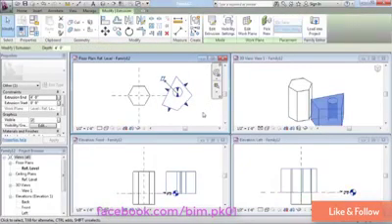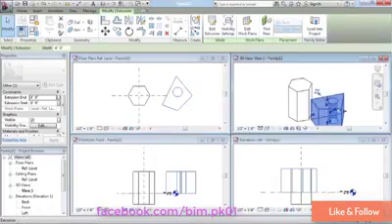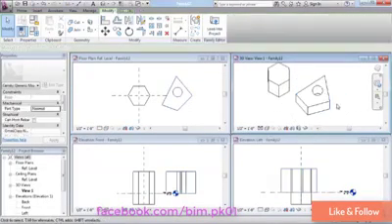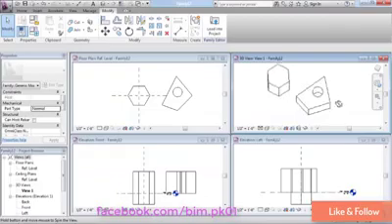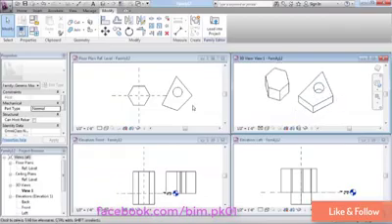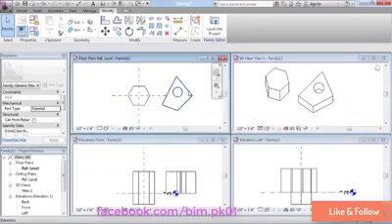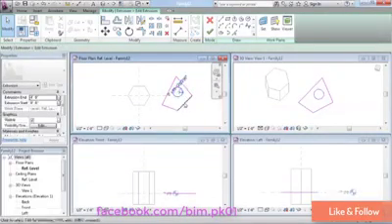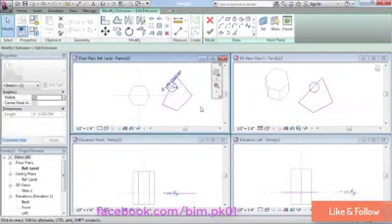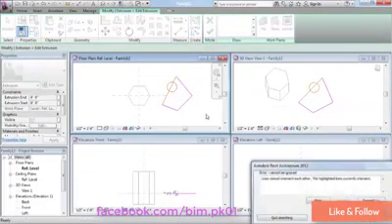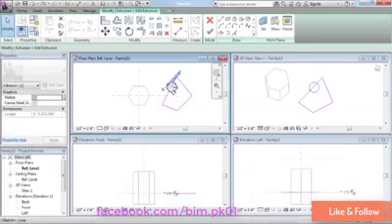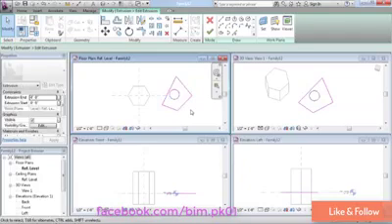And then it will extrude as a hollow, basically. You can have as many closed loops as you want inside that extrusion. It's all in the single sketch. But what they can't do is overlap one another. If I took this circle and I did this and I try to finish it, Revit will complain about that too. As long as you make a valid sketch, really pretty much any shape that you like is acceptable.